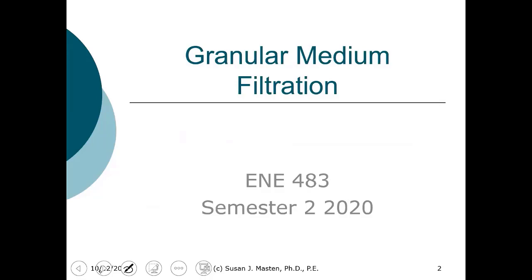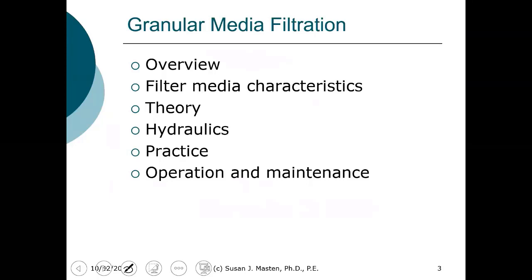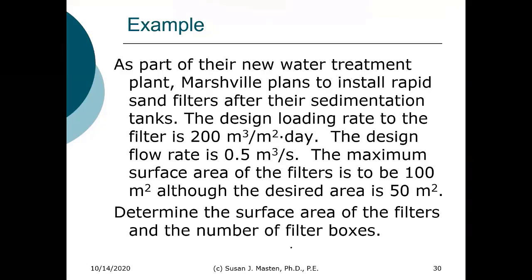So what we'll be talking about is granular media filtration. In this segment, we'll look at the design of a rapid sand filter, focusing on the calculation of the hydraulics of the clean filter bed and the hydraulics during backwash. What I'd like to do now is go through an example. This will take the rest of today and on Friday. What I'm hoping to do is we'll get through the head loss calculations for a clean filter bed.